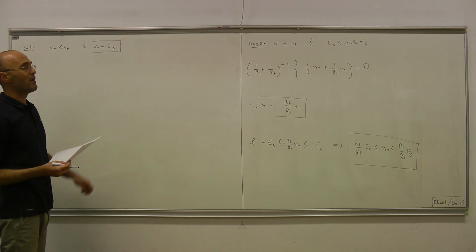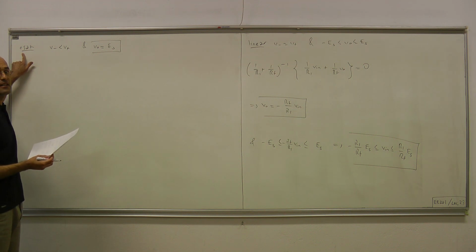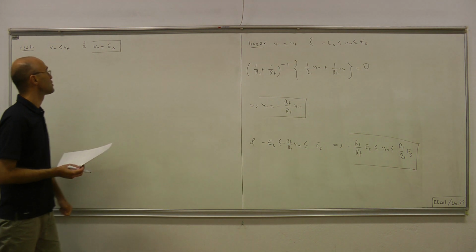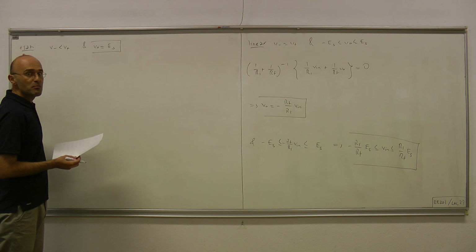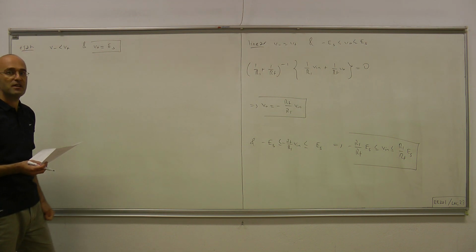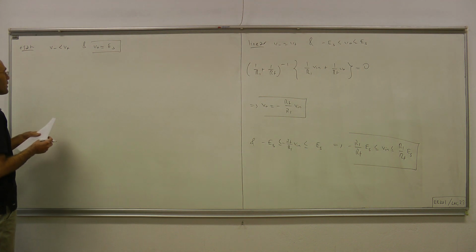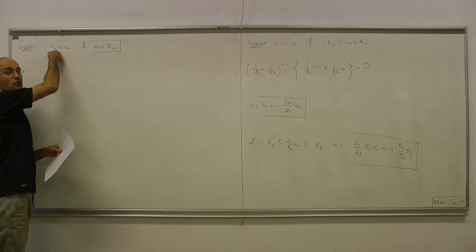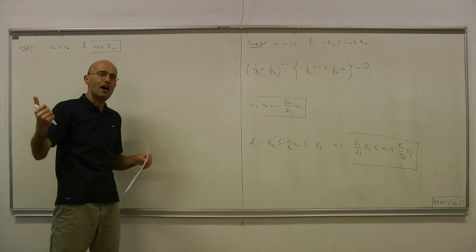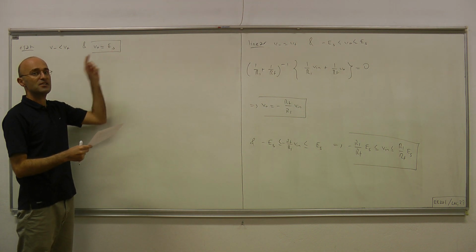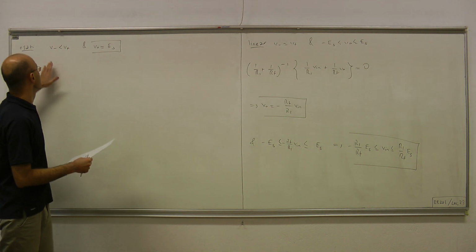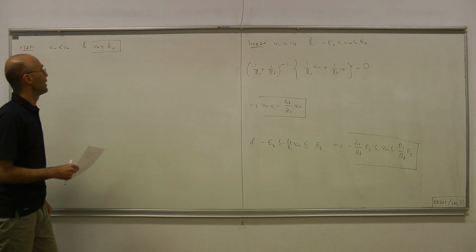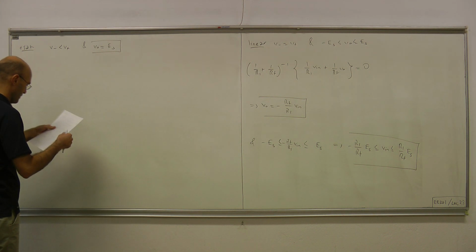Okay. Now, therefore, by analysis of positive saturation, all we need to figure out is the condition on input voltage so that the op-amp is in the positive saturation region, or the output voltage is fixed at ES. For that, we take the expression of V minus and V plus in terms of V in and V out. Now, V out is fixed at ES, therefore we replace V out with ES, and therefore everything would be in terms of V in. Okay. And that's what we need. We need a condition on V in so that the op-amp is in the positive saturation region.